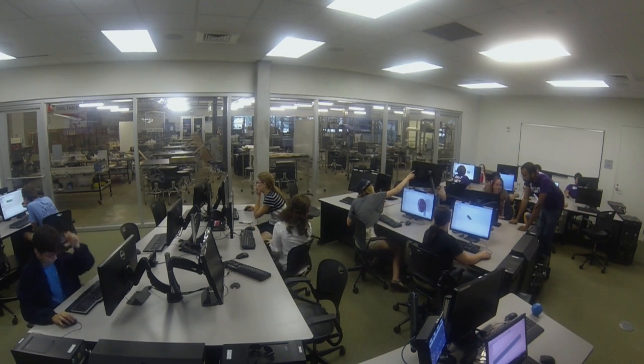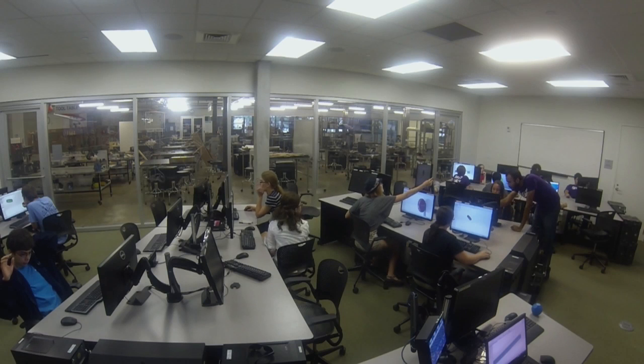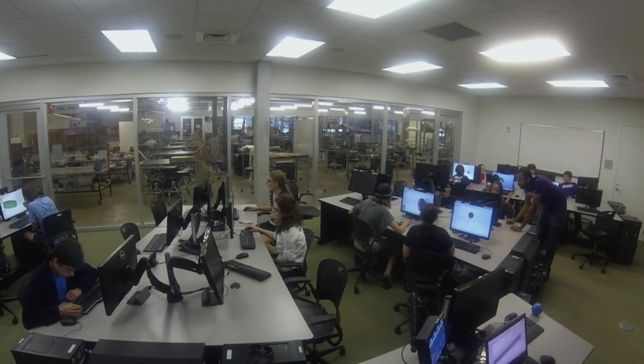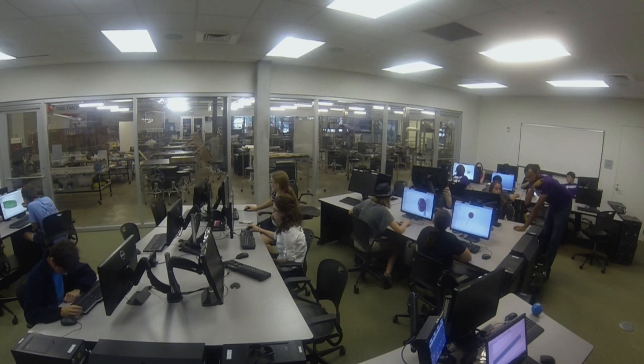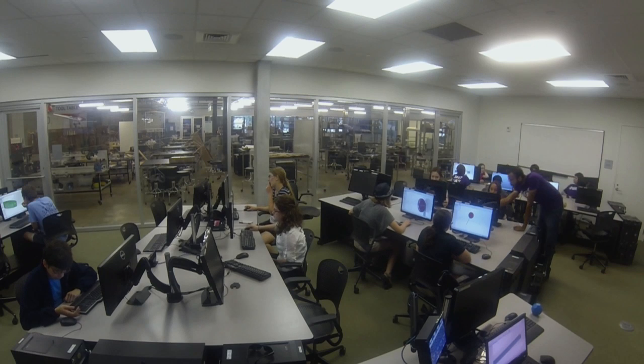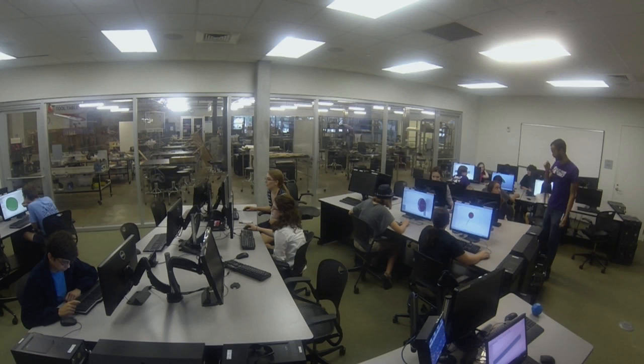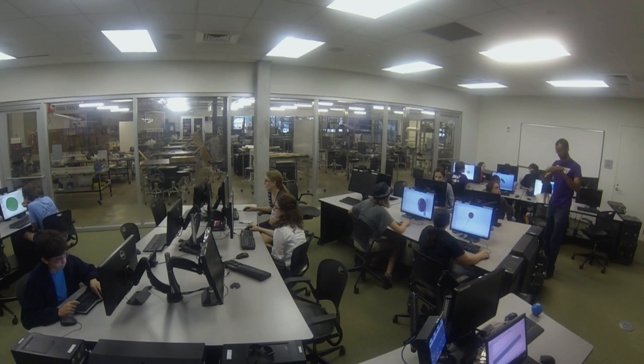Okay. So did you put a hole anywhere in this? I think so. That's probably your best idea. So in the same way that we were doing that hole earlier on the round pipe, where you do the reference geometry, put one into the corner somewhere and put a hole that's roughly the same diameter as whatever your stick is. And then when you go to mate, you'll just be able to tell it to go right into it, and it'll do it properly.